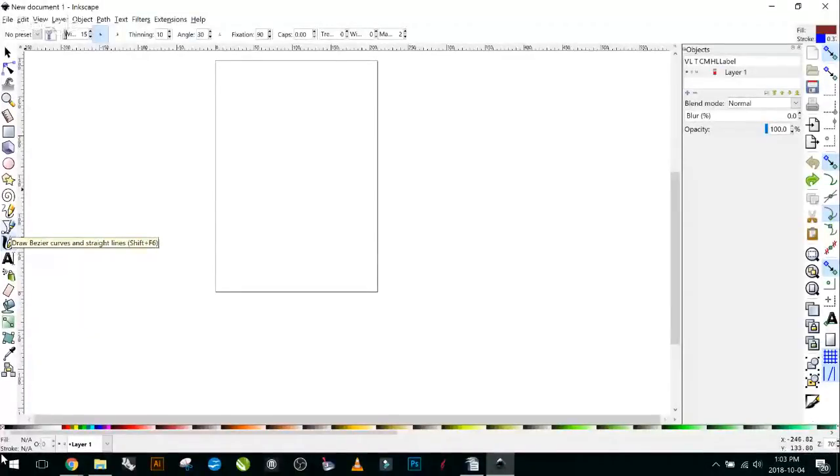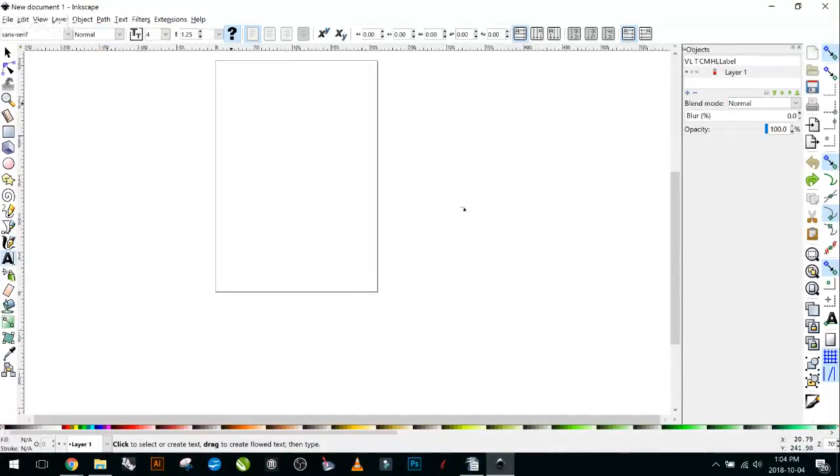To start, we'll start with our font here. We always like to start with font because it's probably going to be the first thing you do with your laser: writing font. Who doesn't like to put their names on pieces of wood and other cool products? So go ahead, click your font down here.